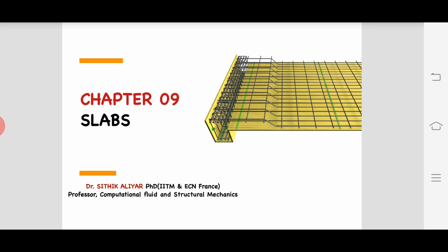I have shown a picture here. There are two types of slabs. Here, if you see, they have cranked the slab, cranked bars. And one more thing I wish to tell you: what you are going to provide is nothing but reinforcement again, correct? In designing a slab, in most cases the slab will be 100 mm to 150 mm thick for all residential cases. If you are going for port and harbor structures, maybe 400 to 500 mm thickness will be there.